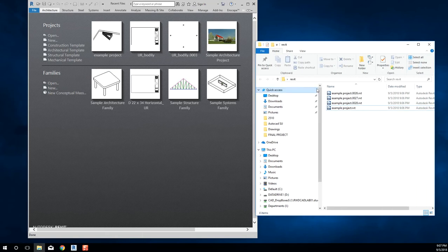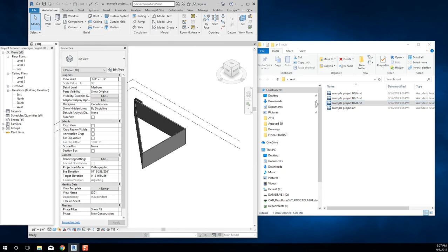One thing I don't like about Revit is that these backup files, if you double click on one, guess what happens? It opens up and it looks like a regular working file, right? The problem with this is that if you save it and it's somewhat of an older backup file, meaning you had a lot of time between your saves, it will overwrite your current file, right? Essentially killing all of your work from the point of that last save to where you were at, right?